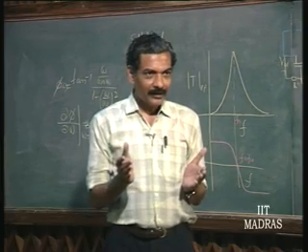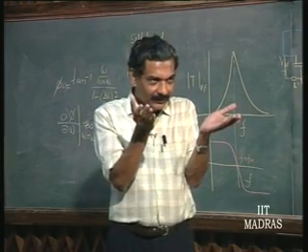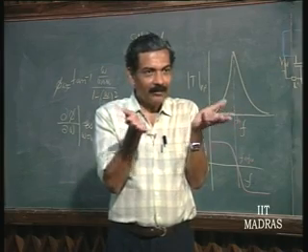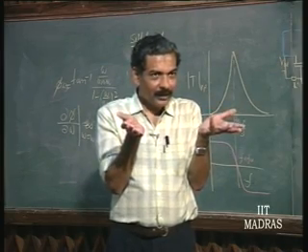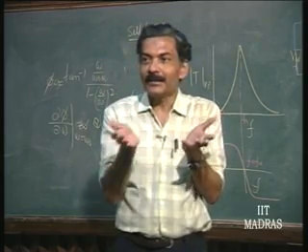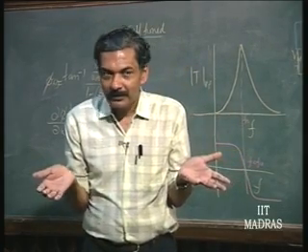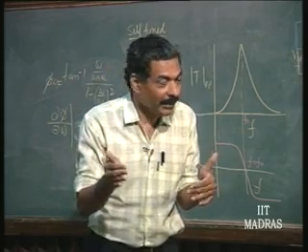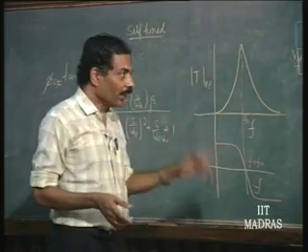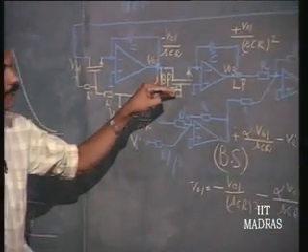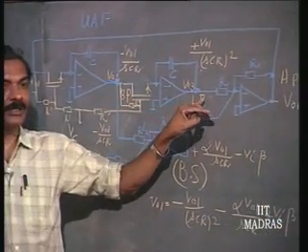We said our phase detector that we had used earlier, the multiplier type of phase detector or AND gate phase detector, was not capable of detecting phase, that is leading and lagging phase, if it is starting from 0. We had to have a quiescent phase shift of 90 degrees. That means it is advisable not to use the output of the band pass, but we must use additional phase shift, which is already available to us.